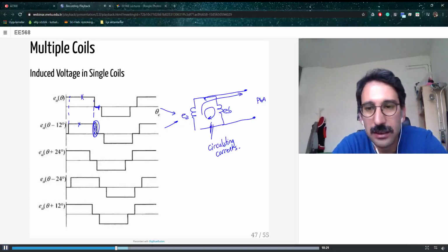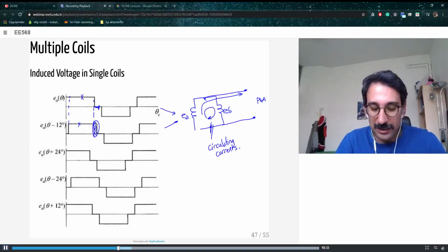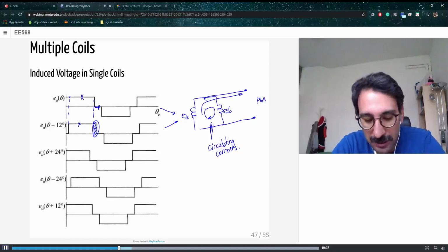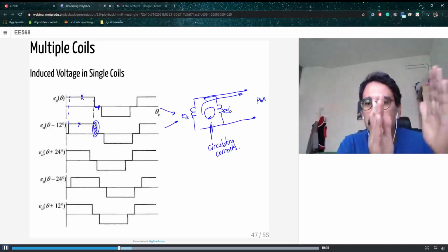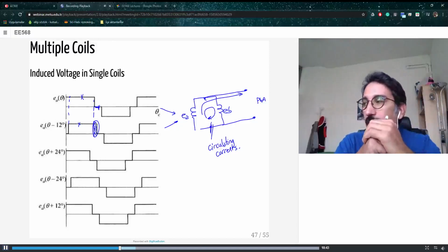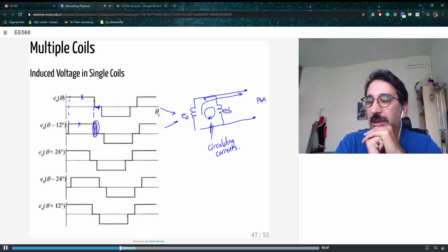It is not allowed to have parallels between those coils if you have even a slight voltage difference between them. In practical cases, even if you want the ideal voltage, there can be non-idealities in manufacturing. The coil positions can be shifted, the air gap can be slightly longer or shorter, the magnets at that coil can be slightly stronger than the other one.